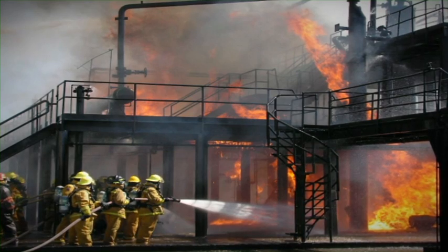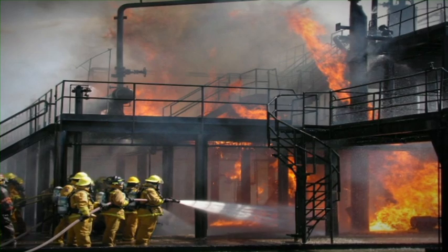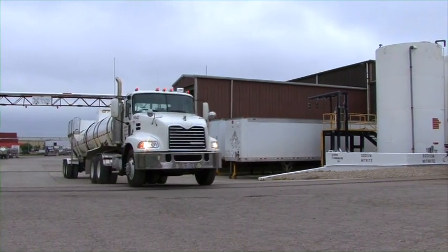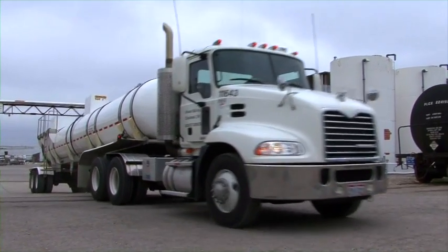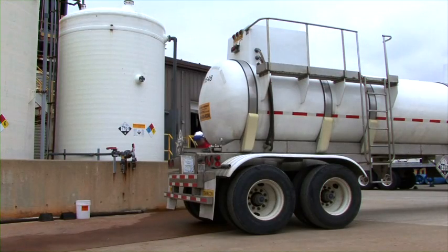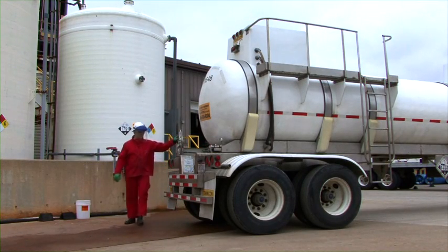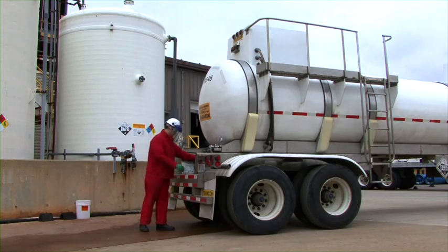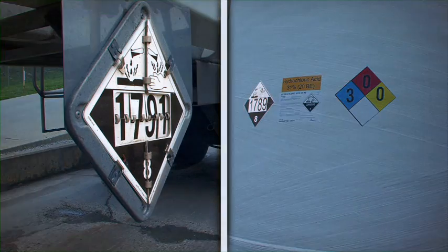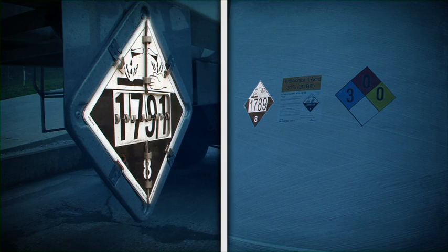Accidental mixing of incompatible chemicals can result in severe consequences. Clear communications and coordination between the truck driver and operations personnel is important for a safe unload process. Ensure that your company establishes safe unloading procedures. Offloading sodium hypochlorite into the wrong tank can lead to a very dangerous reaction, potentially releasing chlorine gas, which can result in serious personnel injuries or even fatalities.